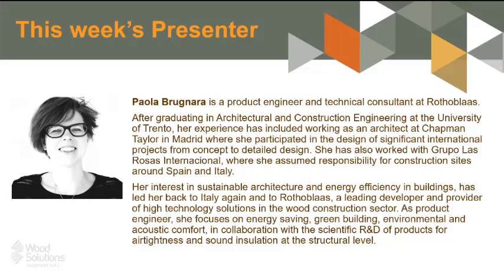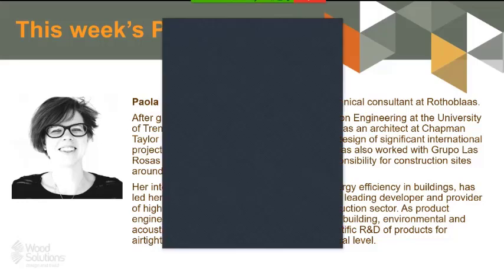They are born and calibrated for heavier materials and stiffer materials. And timber, we know, is intrinsically better from the acoustic point of view, at least in the medium and high frequencies. It has, as Paola pointed out at the beginning, a little limitation in the low frequencies, intrinsic to its nature of being a lightweight material. But the solutions are available and ready, and there is evidence also from testing on site.